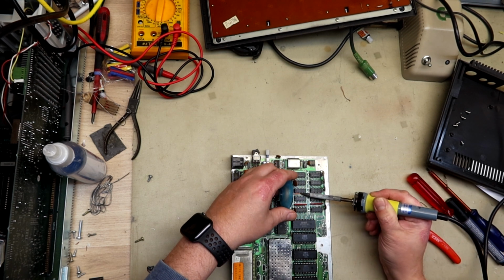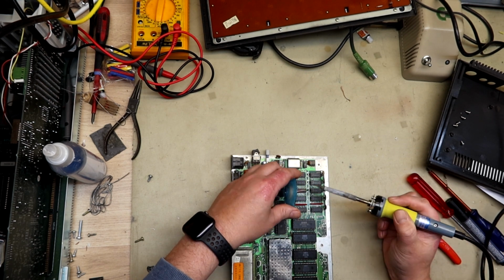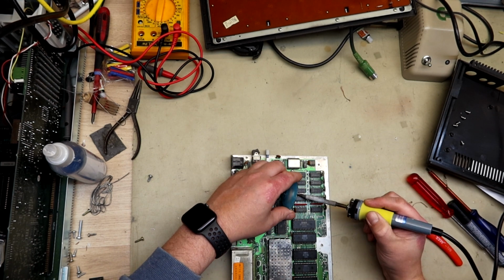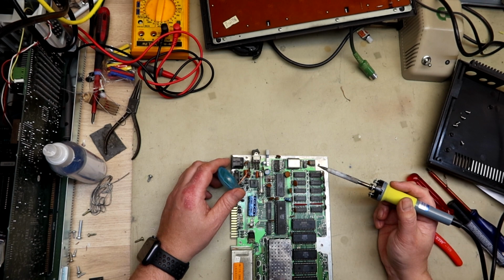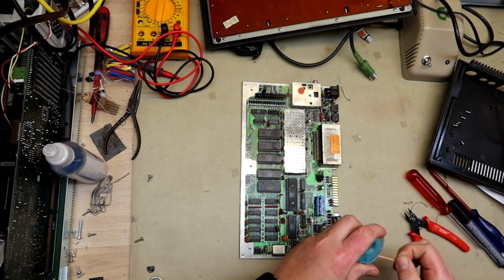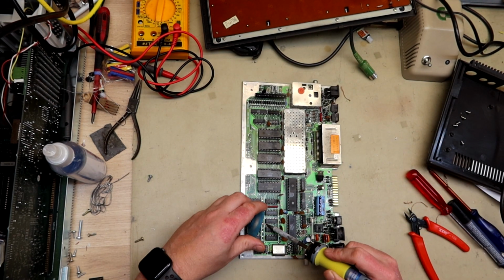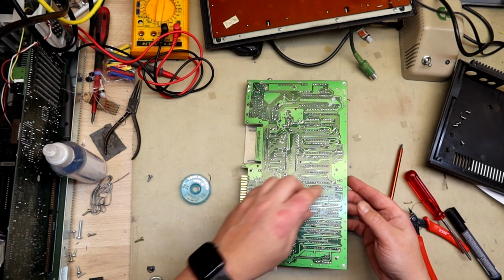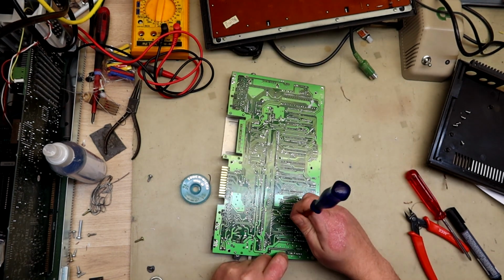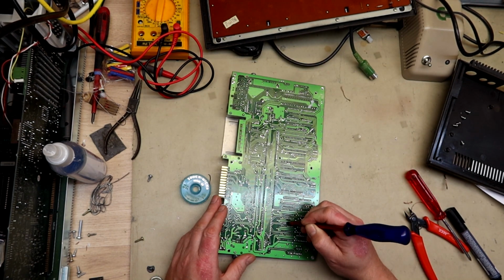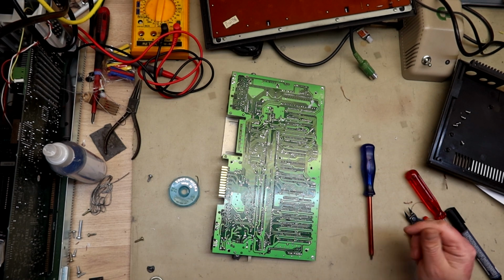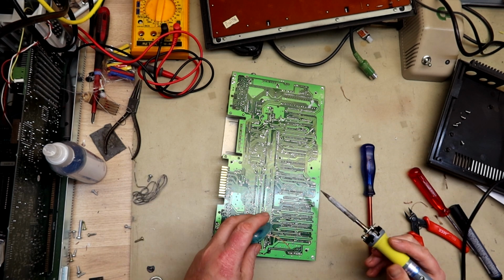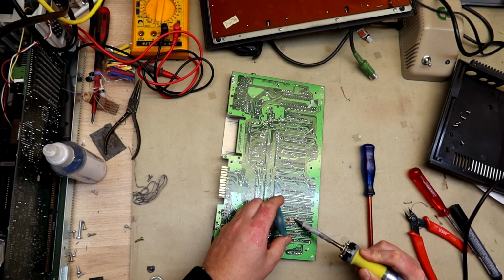Back in school we learned that using solder braid was much easier on the solder pads and also on the components, as you would require less heat and you also didn't have the extreme suction that you have with a suction pump. But this is actually a mixed experience, because sometimes when the solder braid doesn't suck too well, you have to use more heat. And as we see here, we do have some pads where I have to apply some more solder and take a second turn with the solder braid.